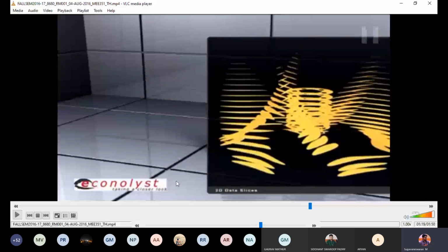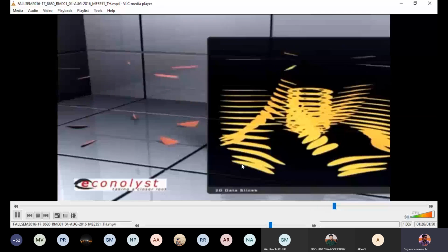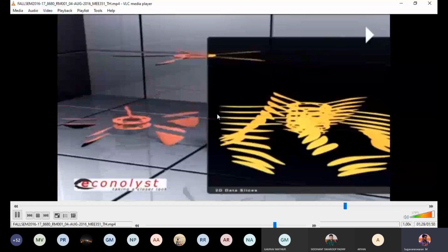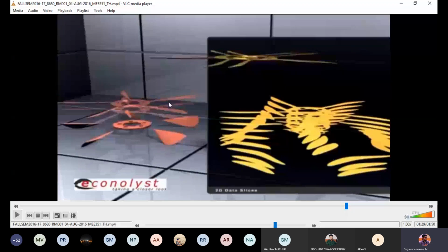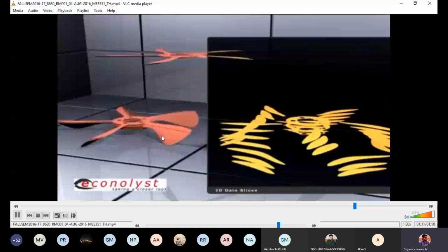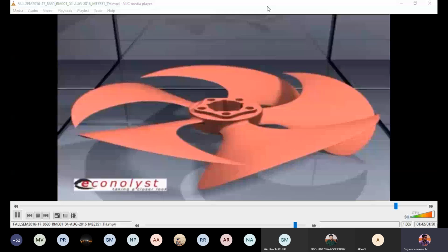On completion, the slice files are then sent to the additive layer manufacturing system one by one, where they're reconstructed from the bottom up. You can see from the video, each and every slice is a flat face. But when you stack the flat faces in sequential manner, you are able to achieve a solid three-dimensional part. This process could be done using laser sintering, selective laser melting, stereolithography, 3D printing, fused deposition modeling, or a whole range of different additive layer manufacturing technologies.